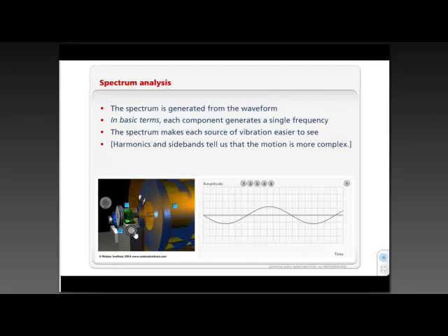We like to see what the vibration's like to begin with, but we love to see how it's changed, because if I can see a change in one part of the signal, in one part of the vibration, I can say it's got to do with unbalance and not a bearing problem. Anyway, so there's the vibration that's just from the shaft, and there's the vibration just from the bearing. Now, it's a simplification of what it looks like, but we're just going to say that there's one unique source of vibration from those bearings.